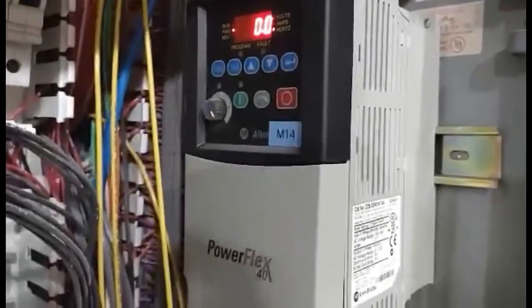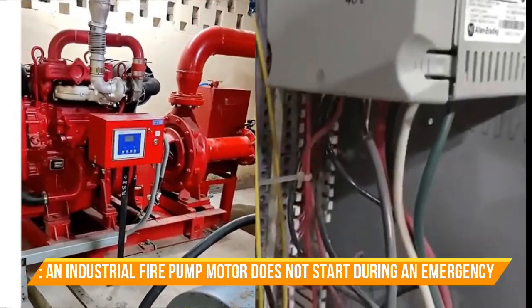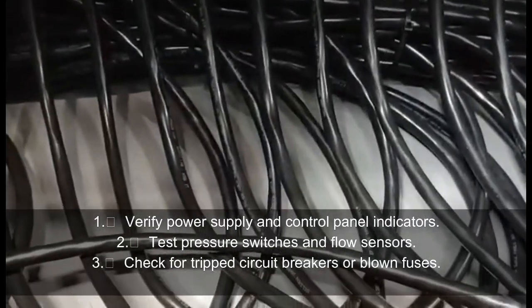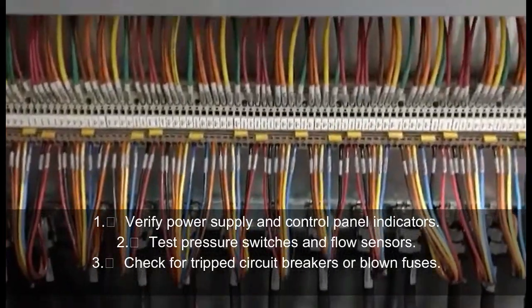Next question. An industrial fire pump motor does not start during an emergency. What could be the cause? Answer. Number 1, verify power supply and control panel indicators. Number 2, test pressure switches and flow sensors.